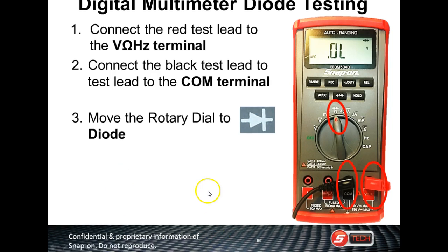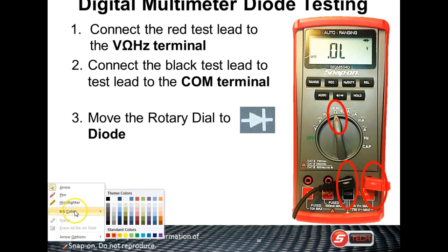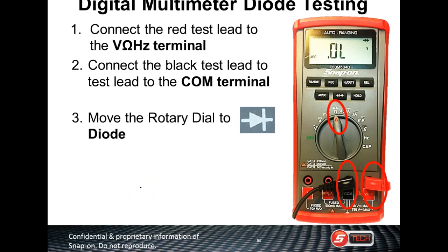Now, what does a diode do? Yeah, it's a check valve. If you're familiar with check valves in any fluid system, it just lets current flow in one direction. We use it for protection and stuff like that, but one of its main uses is to turn AC into DC. In your car, you've got a set of rectifiers because you have an AC alternator, but your car operates off of DC, right?